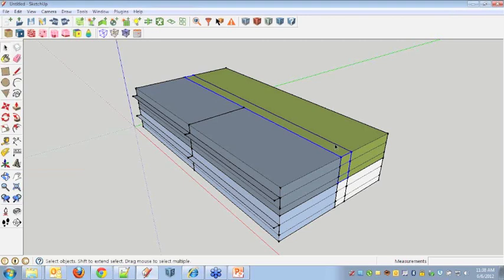So what will happen is when we make a thermal zone, we'll add the loads from the corridor and the banquet, and we'll make a weighted average, or that's actually an additive process to put those together, so that you don't have to keep the separate spreadsheet to explain to people where you got the values for your thermal zone. It's a more traceable, transparent process.